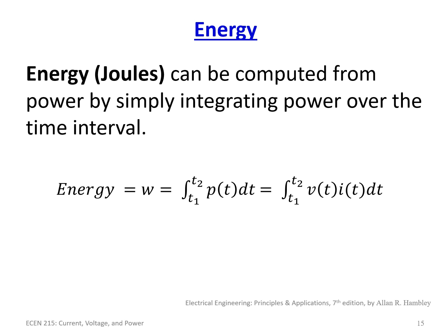Energy in the end is the integration of power over the specified time. And this is simply going to be in joules, so you're getting rid of the seconds component effectively. So you're just going to integrate P of t dt from time 1 to time 2, whatever it is, or you can simply do the integral of v(t) i(t) dt.